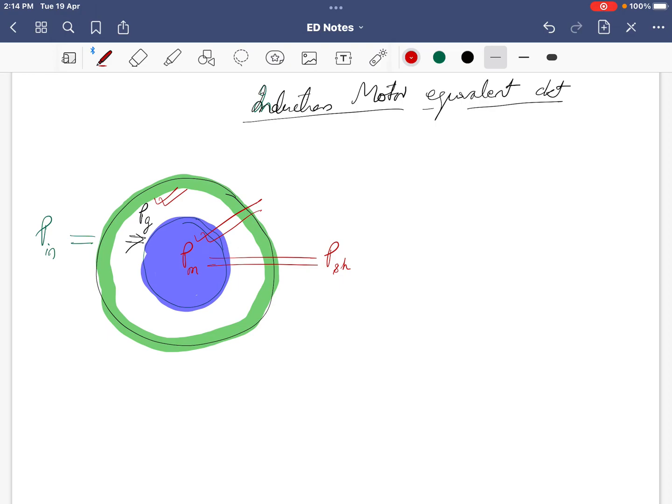Now as we discussed, there is a resistance on the stator. So the stator obviously has a resistance RS, and the flux usually links between the coils like this, within the stator itself. These are the leakage flux, and this leakage flux leads to the leakage reactance. So we can have XS as a leakage reactance, and there is another flux between the stator and the rotor, called mutual flux phi m. I will come to it a little bit later.